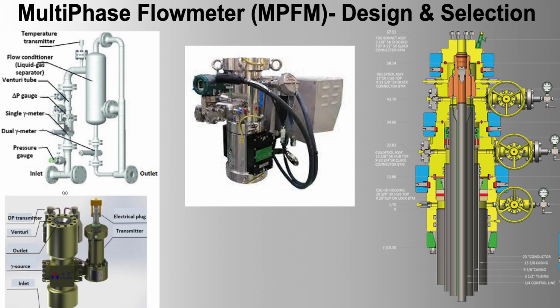2. Enhanced troubleshooting. Scenario: a sudden drop in oil production is observed at the central facility. Benefit: with MPFMs installed, operators can quickly identify which well cluster is underperforming and take targeted action to address the issue, minimizing downtime and production loss.